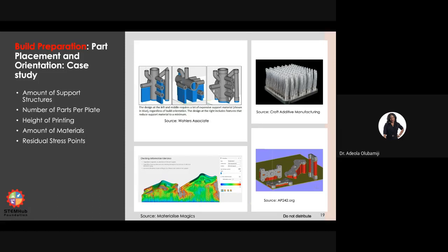So for any designer who is doing additive manufacturing, you must consider your support structures. It's very critical if that technology requires it. Another way to predict whether what you have designed is going to print, and whether your support structures are enough, is running a simulation. Here I'm showing an example of a simulation that can be run. This is one part with the orientation slightly changed. You can see the red areas. Those red areas are where you're going to have residual stress buildup. So those areas are susceptible to residual stress, and the part could break during printing or after printing.